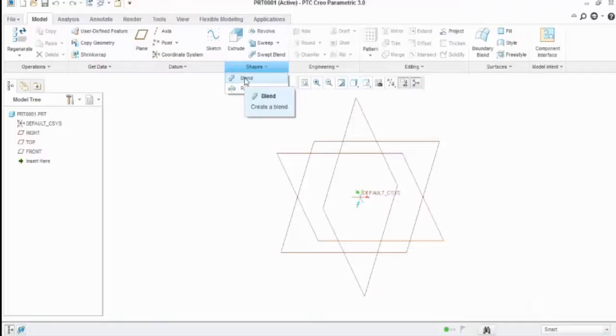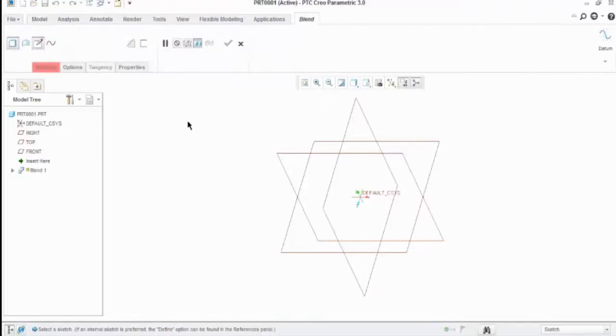This is the blend feature. Create a blend feature. Click on here. Basically in blend you are creating some closed objects at specified distances. That distance can be from planes. So multiple objects you can draw here, but the condition is the corner edges of the elements should be the same all the time.